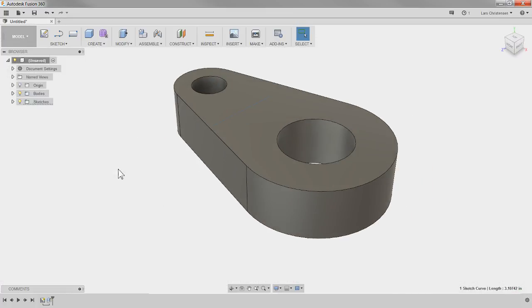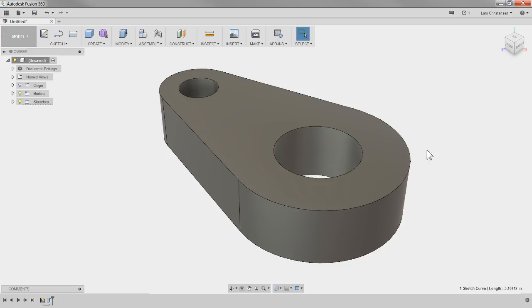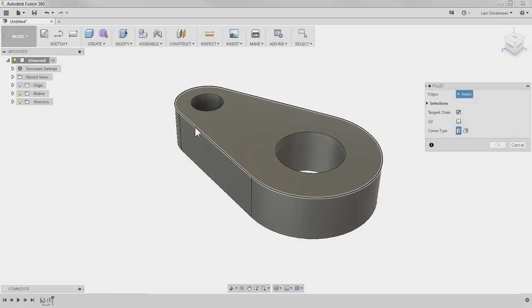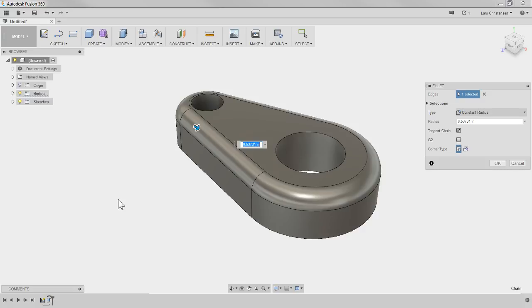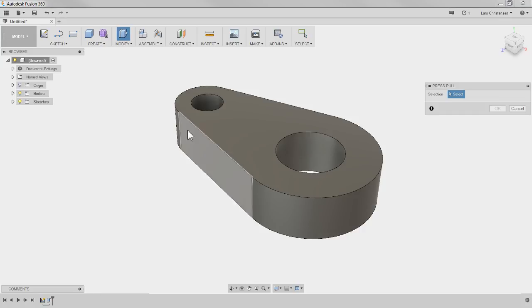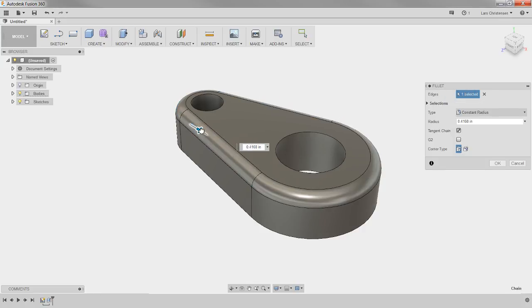Now the last one in what I will call the beginner series is, well, I put it in as F for fillet. So hit F and you can place a fillet on a part. But it's really not necessary to know about the F because the Q command will do the same thing, right? The same thing we use to press pull, the Q will actually do multiple things. And there was a live stream about that, so you can definitely check that out.